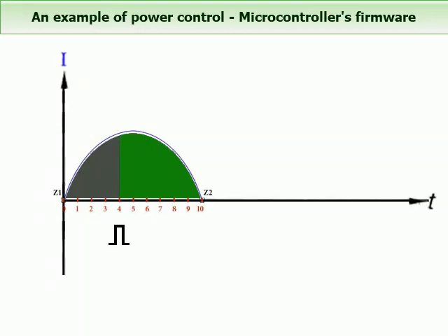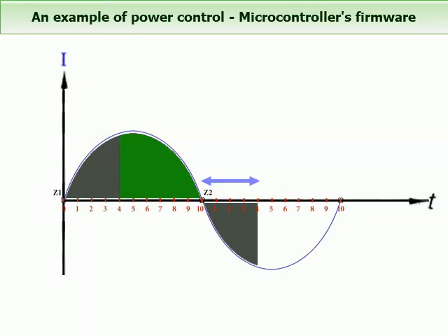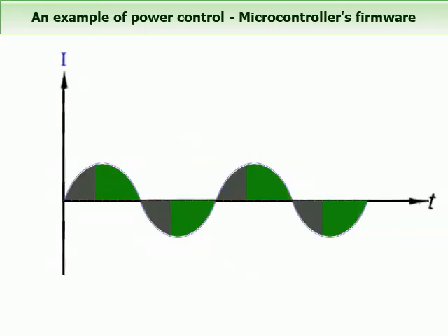The next interrupt occurs at the next zero point, Z2, with the device already disconnected. Again, the microcontroller goes to execute the interrupt procedure, where it waits 4 milliseconds with the device already off, triggers the TRIAC once, and leaves the interrupt procedure back to the endless loop waiting for the next interrupt on Z3. Just as in the first half wave, the device works for only 6 milliseconds in the second half wave, and this is what will happen in all subsequent half waves.